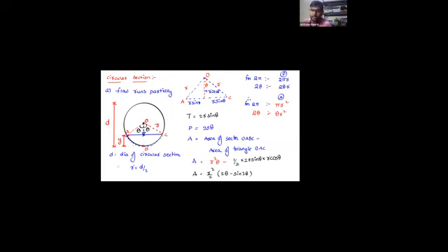So how I have to find out the flow dimensions over here: number 1, top width. What is the top width over here? AC is nothing but the top width. And what about the wetted perimeter? For total circle 2 pi r, for 2 theta, 2 theta r. Similarly, how to determine the area? So once I know the top width, wetted perimeter and area, now I can find out the hydraulic depth and hydraulic radius. Yes or no?